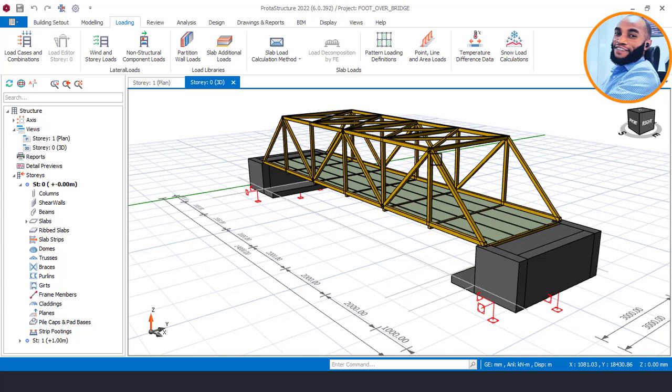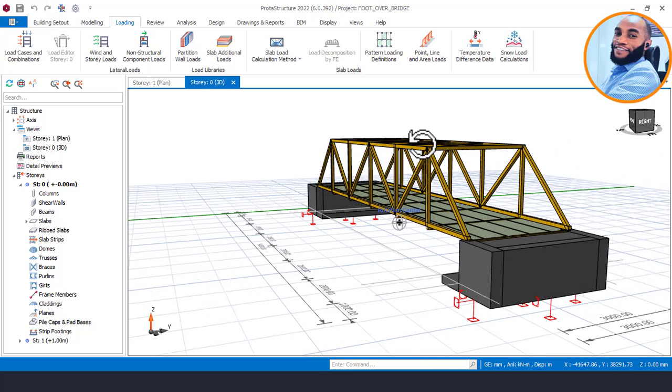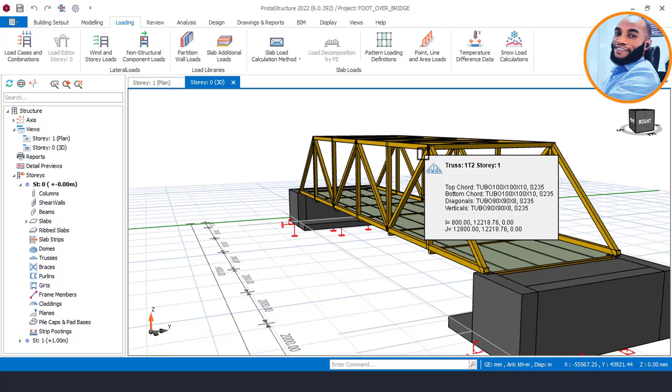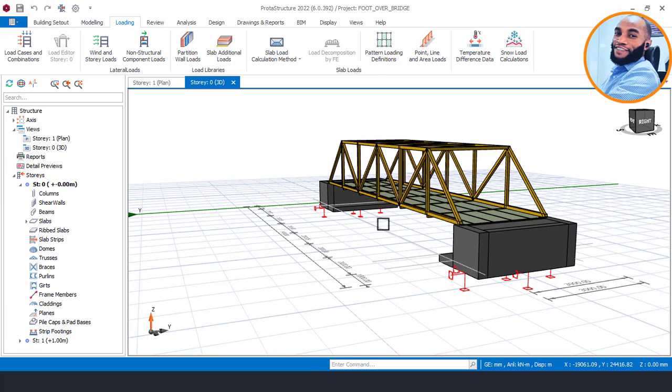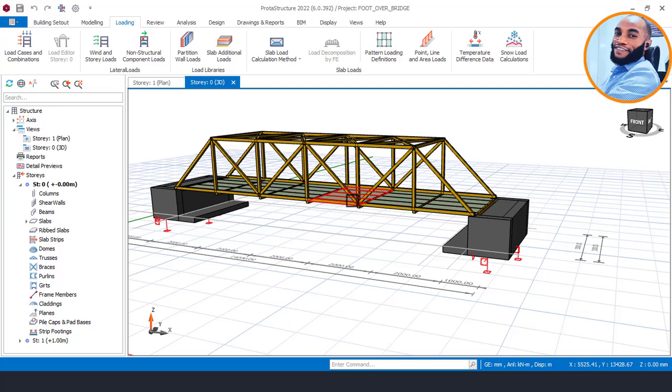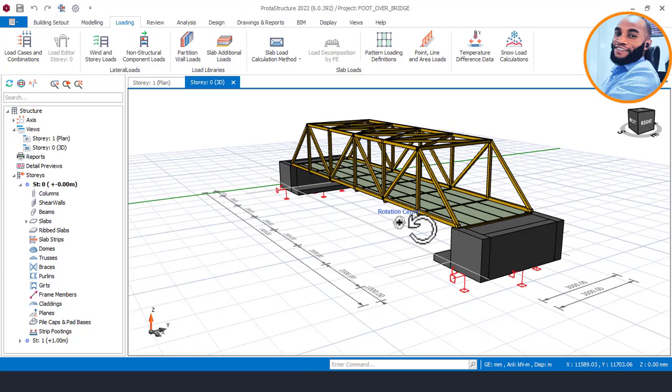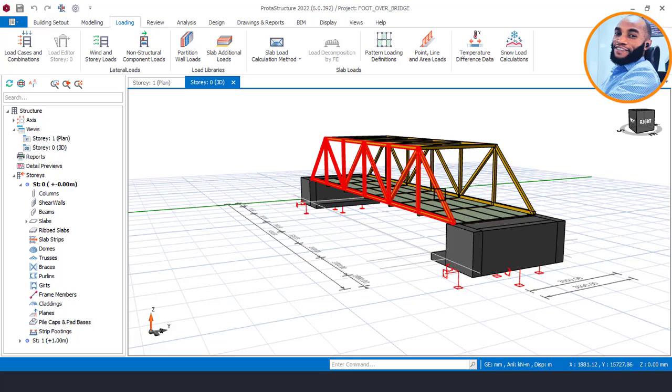After wind load, you must also consider thermal actions, which is temperature loading, and then the possible accidental actions from impact, from vehicle impact or another. Then the other one is dynamic water pressure, but only if your bridge is crossing water bodies. That's when you're going to apply that to your pedestrian or footover bridge design.